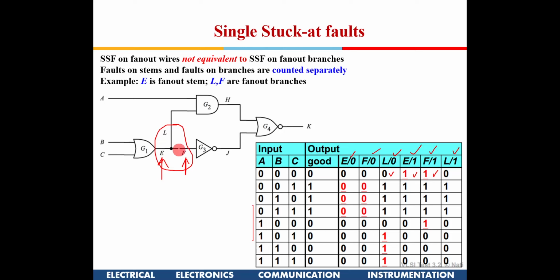The other way around also, so you will see from this table. When branching is happening like this, each fault needs to be considered as not dependent on each other. So you have to consider that as a different fault site, and accordingly make a truth table and see what test vectors are really required to identify those particular faults.